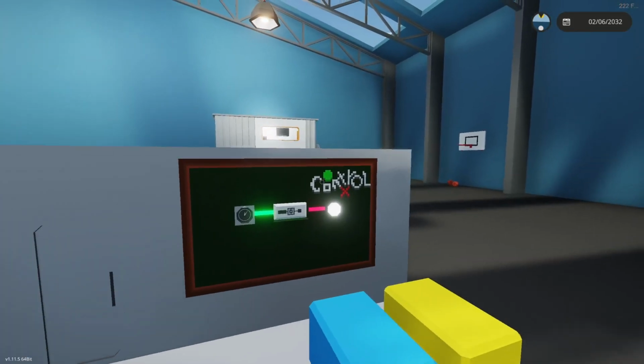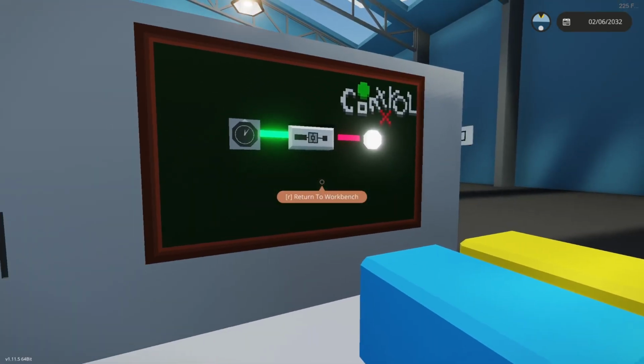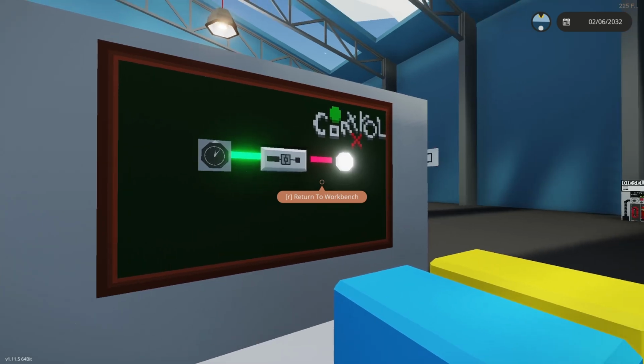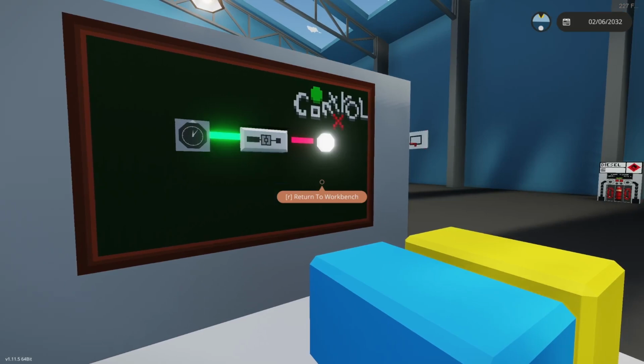that range. Now, what I was mentioning earlier, you could use a not block to invert it, or you can actually put the high value in the low slot and your low value in the high slot, and that would also invert it. Those are things you can do, but that's going to take experimentation to show you what it can do, and that is not what I'm trying to cover, but I figured I'd let you know it's something you can do, because if you were to take a not block and put it after this, you would actually have the light on at night, like for running lights on the truck, and off during the day.